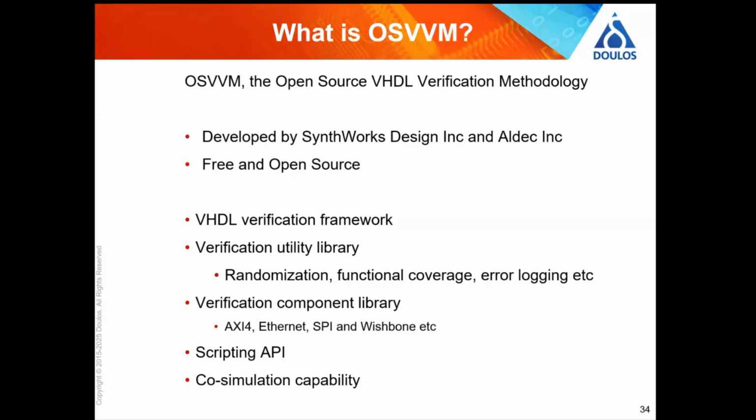There, you get supplied with a bunch of bus functional models that do standard protocols, so AXI, Ethernet, etc. Because a big advantage of this idea of transactions and using a methodology is, of course, you can get pre-designed test bench IP. If your chip has a certain interface on it, you need a corresponding BFM, and it'll just work with any design that has that interface on it.